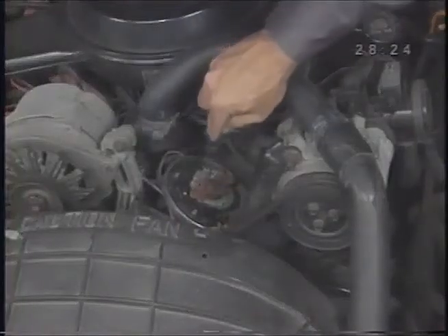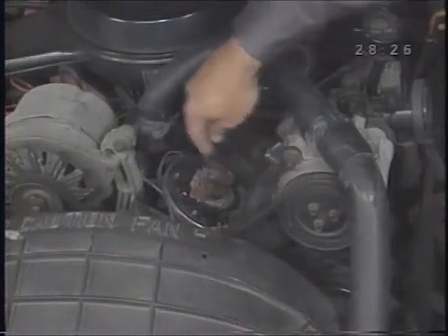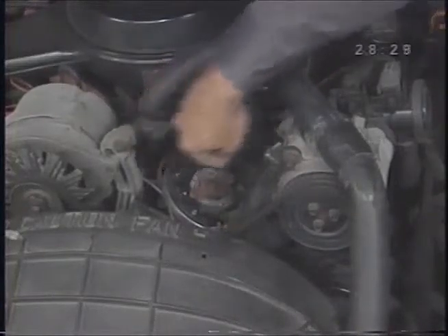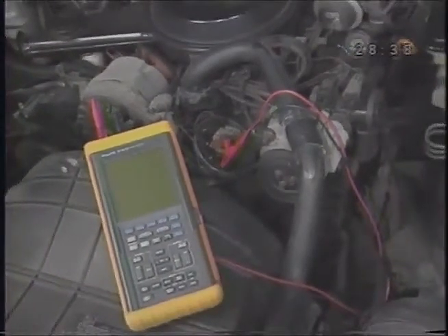To read this signal, you'll need to remove the distributor cap and rotor and disconnect the pickup from the electronic ignition module. Connect Scopemeter's Channel A probe and ground lead to the wires from the distributor pickup. It doesn't matter which lead you connect to which wire.